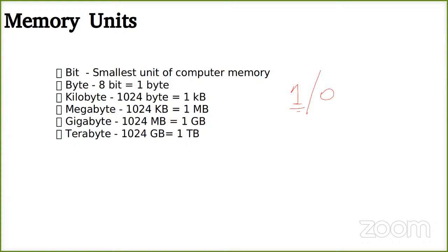Okay, so when I talk of high logic and low logic, it is maybe if your system is at 5 volts, it is plus 5, otherwise it is 0. If the system is at 3.3 volts, your 1 is 3.3, your 0 is 0. If it is 1.8 volts, this is your high, this is low logic. Okay, so please remember 1 and 0 are logic levels.